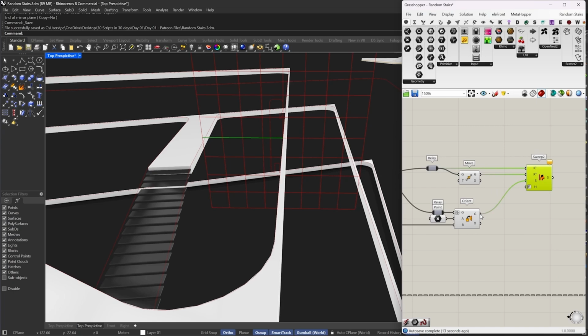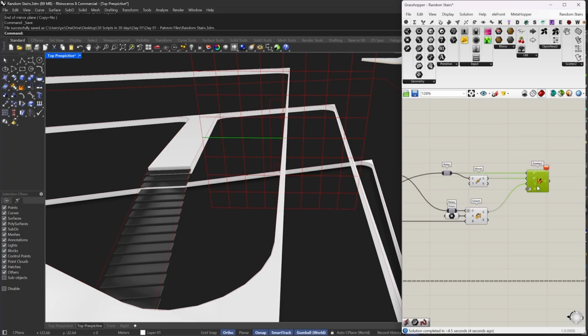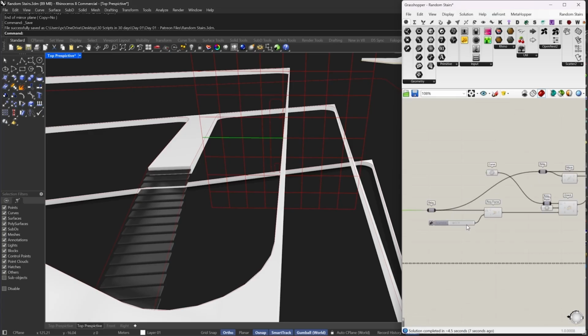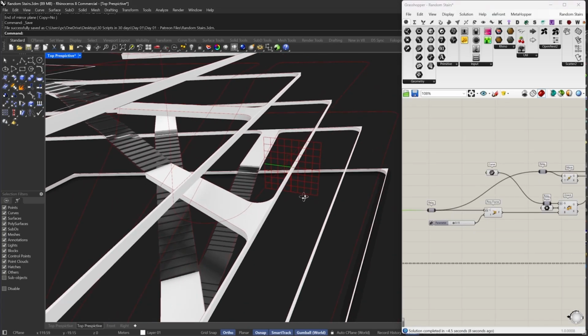This is the most intense part, and sometimes it's working, sometimes it's having an issue. This is why usually I create a dam in here, just because if for some reason I changed the curve or changed anything in the early stages, I can have all the edits that I want, and then figure things out later.